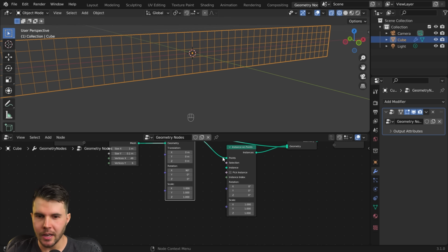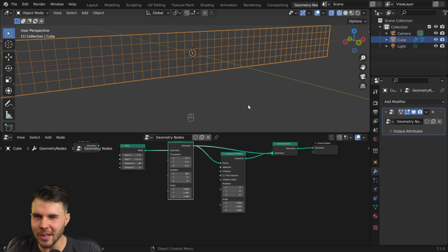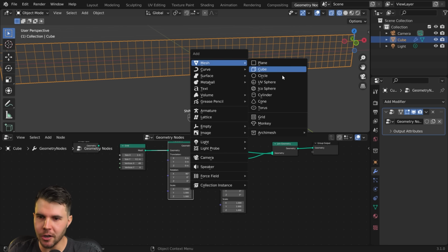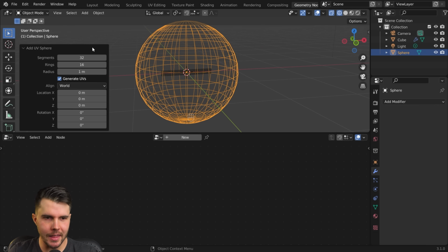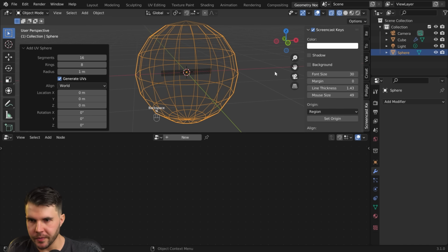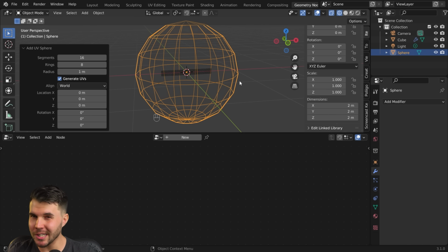Now you could actually create a little bulb within geometry nodes. I know you can do that, guys, but we also want to do some fancy stuff with materials and reference different objects. So it's much easier if it's its own object. So out here, I'm going to add a new object, UV sphere. And then in the properties, I don't want it to be this high res because we're going to be referencing it hundreds of times. So let's go 16 segments by 8. And in your items over here, the dimensions, you can see it comes in at like 2 meters, like the size of an adult.